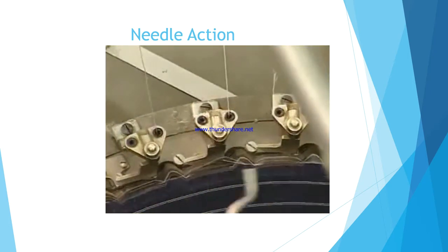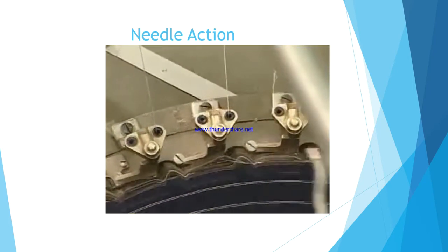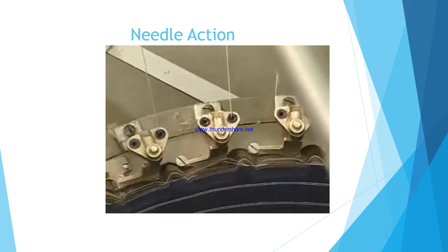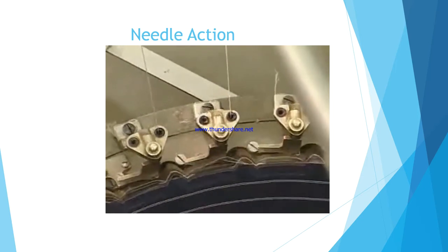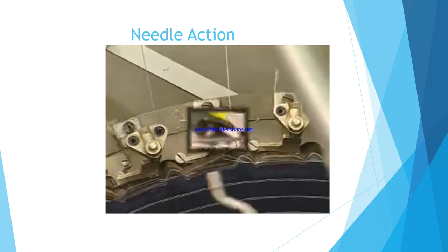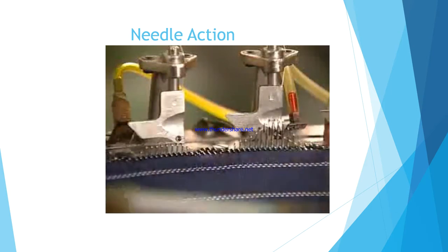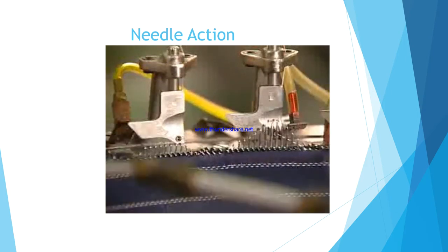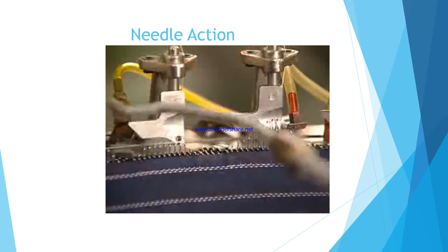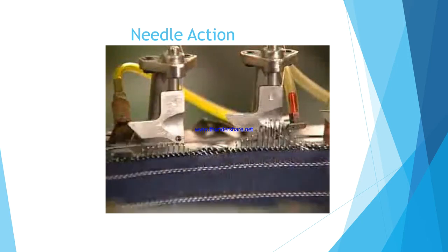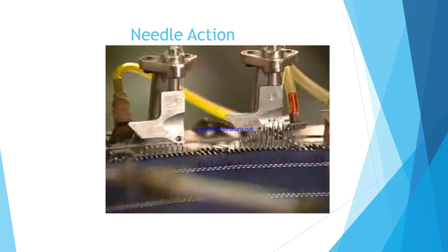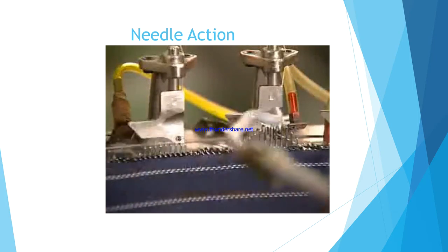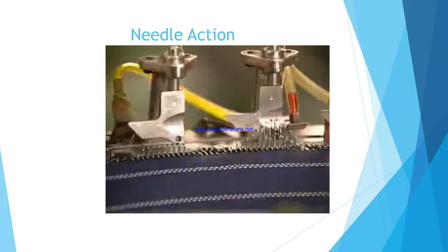The intricate action of knitting, where needles form loops, occurs at the middle of the machine, between the take-up and the yarn feeding. A close-up shows you how, with circular weft knitting, needles knit one after the other in a sequence for each yarn. Notice how loops are formed horizontally by needles knitting around the cylinder, forming a tube.